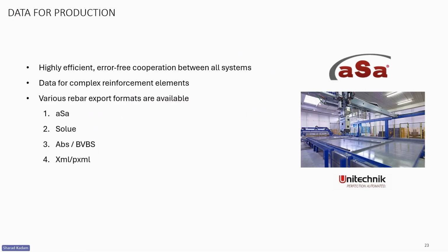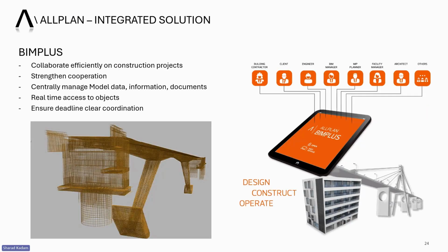And once the drawing portion is done, we need to give the rebar export format. So we have various rebar export formats available. We have PXML, we have BVBS, ABS, ASA format available. So any kind of rebar output format other than Excel, PDF, and DWG. So all these formats, the machining formats are available.